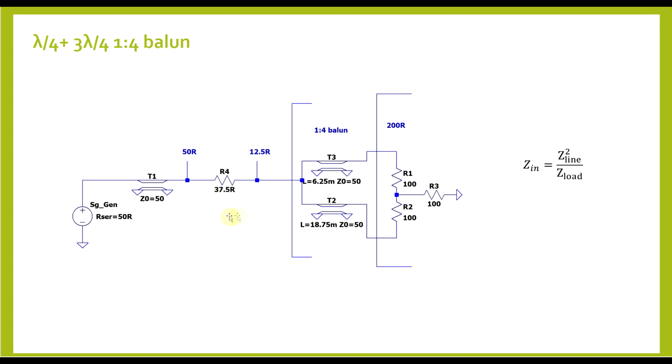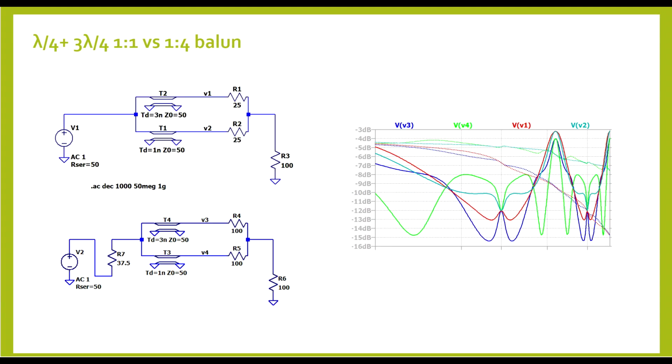matched. Now, before running the test, we can look into the simulator and see that with this sort of circuitry, the expected voltages that we should get on our 200 ohm termination are exactly the same that we should be getting into 50 ohms with the initial setup. So regardless of which setup is being measured, we should be seeing the exact same voltages.